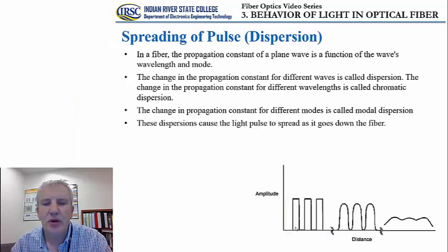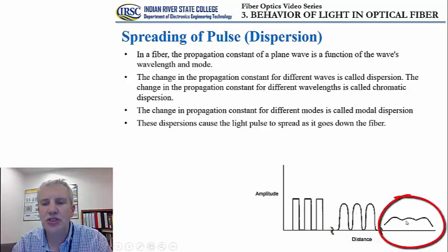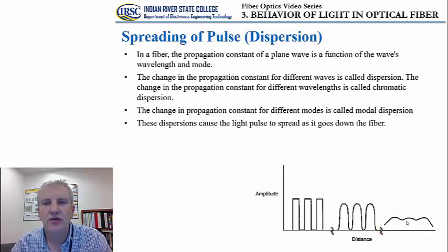As these three pulses are propagating along an optical fiber, due to this dispersion, these pulses are going to change the shape from being perfectly square into being round, and also their duration is going to increase, so they will start spreading over time and they will start merging into each other. So this is going to cause a loss of information and certain errors that would occur in a transfer of information. So this is a very distinctive problem that's related to the dispersion that's occurring in optical fibers.